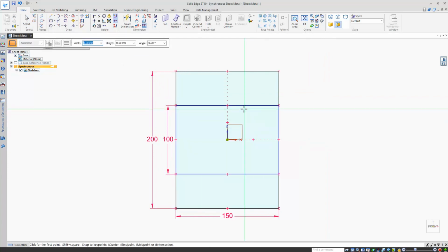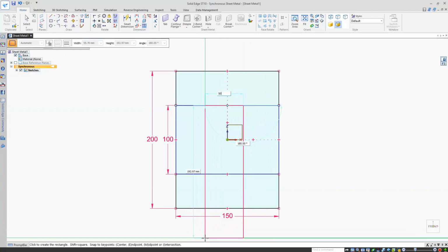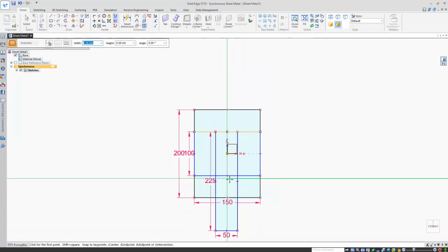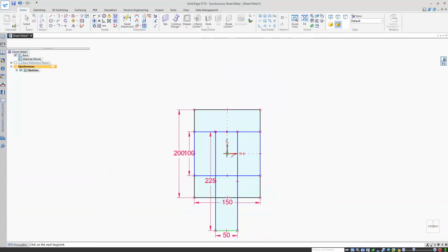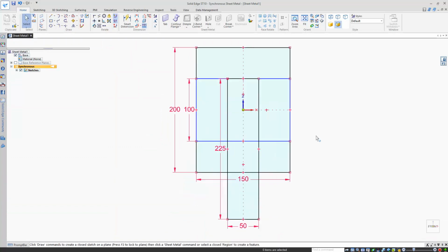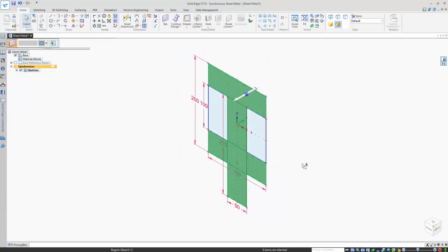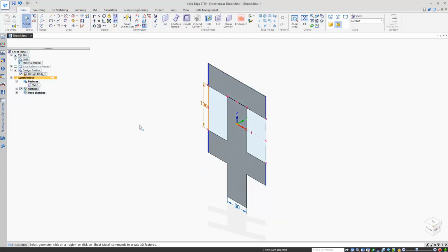And if you're yelling at your screen right now telling me to trim my sketch corners, this video is definitely for you. Because after I'm finished, all I'll need to do is hold down Control and click, and then keep left-clicking on these 6 sketch regions until they're all highlighted. Then I can extrude material, but only by a certain distance. 1mm is enough for now. And my sketches aren't useful anymore. They've served their purpose, so I'll hide them.